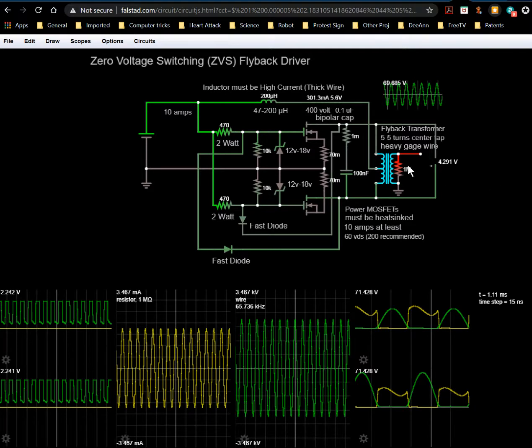But because of that, at first that field has to charge up. So at first there's a real high current surge, but what will happen is it'll get up to some finite level and then kind of level off. Once this field is fully charged, there's still current flowing from the battery because it's DC, but what's happening is that it's just eating up power in the resistance of the coil. You're wasting power, but because you've got that current flowing through it, it continues to generate a magnetic field. And because it's generating a magnetic field, it'll act like an electromagnet.